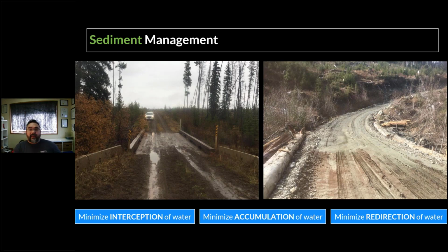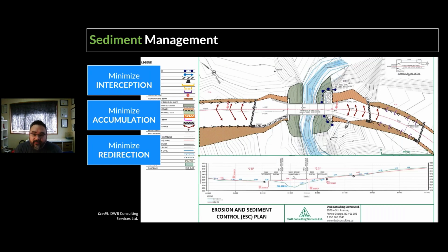And we've started this in BC, and you see it more and more. This is an example from GWB, where the erosion and sediment control plan is actually built right into the bridge design. That's specifying the things we just talked about: the crowns, the grades, the culverts, and the settling areas, maybe some curtains. But lengthening the bridge doesn't always mean getting it out of the swale. Lengthening the bridge can mean that below your riprap or the fill slope that's reposing down from your road, you have more area, like the dark green in the example here, where that water is able to filter through.